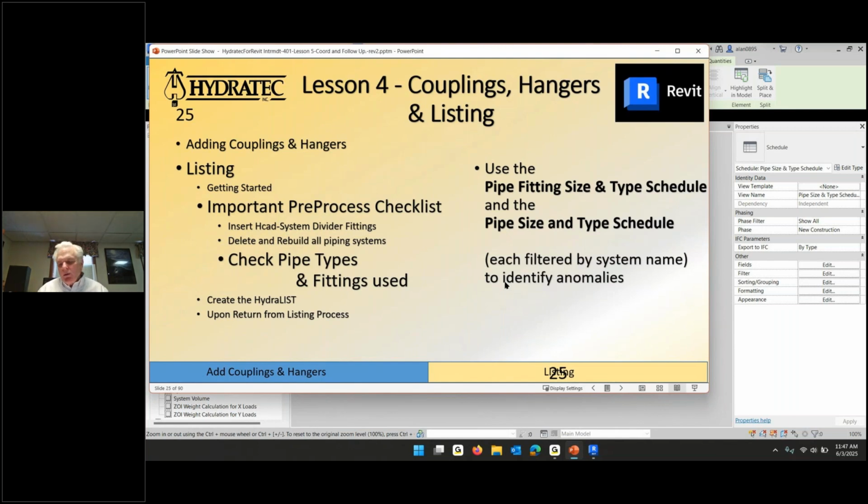If now the thing that you pick is a pipe, it depends on whether you pick the first end or the second end. If you pick near the first end, I don't propose picking at the end, because at the end there's a fitting. So near the first end, the pipe will disappear, the fitting at the first end will stay put, and the fitting at the other end will come to meet it.